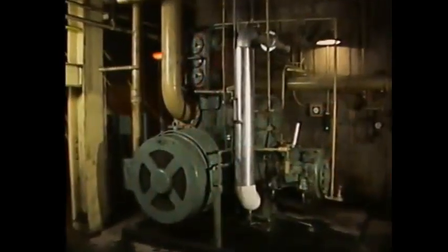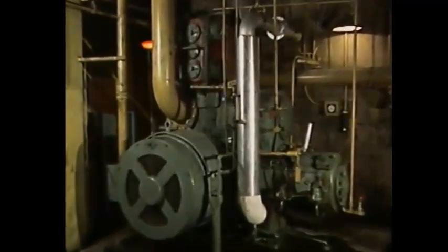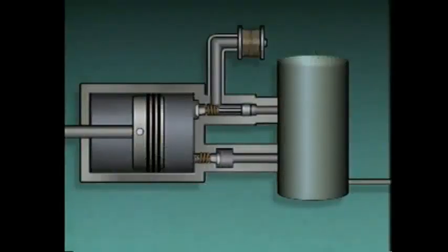Large compressors tend to be more efficient if they operate continually. So one device that is commonly used to prevent overpressurizing the receiver is an inlet valve unloader. This is a simplified illustration of a portion of a compressor system that uses an inlet valve unloader. The unloader consists of a piston and a connecting rod, which is connected to the inlet valve on the compressor. A pressure sensing line is connected from the unloader to the receiver.